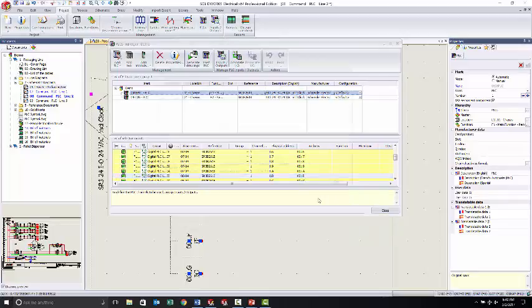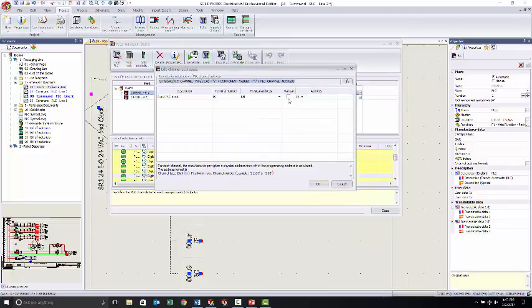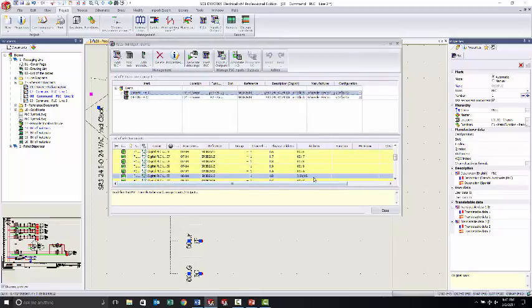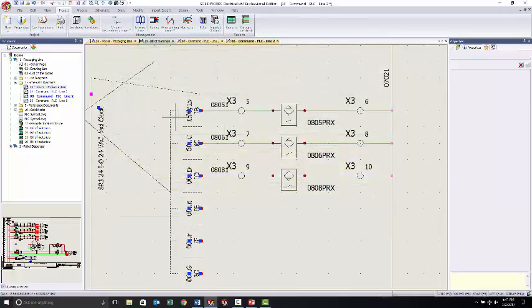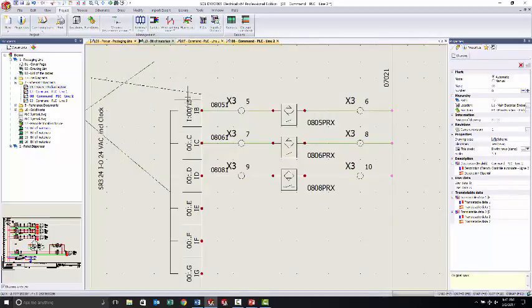I'm going to modify this channel address to put in something that I like, which is more along the lines of my standard that I've always gone with. Maybe it's rack 0, and maybe this is 15. I don't know if this is actually correct, but this is what I'm going to use. Now, it's PLC 5. I'm still old school. What can I say? All right. I could have it be the global variable, whatever the case is. Anyway, the point is that this is what I've got now, this 015.